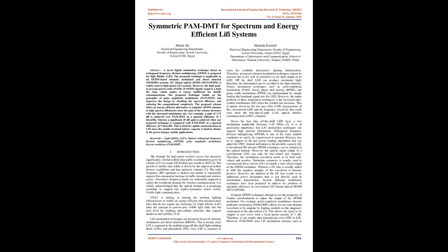The proposed scheme offers an energy-efficient alternative to unipolar OFDM schemes at high spectral efficiencies, since the gain of the scheme increases with the increased modulation size. For example, a gain of 2.75 dB is achieved over PAM-DMT at a spectral efficiency of 1 bit/s/Hz, whereas a significant 20 dB gain is achieved when our proposed technique is compared with PAM-DMT at a spectral efficiency of 5 bit/s/Hz.